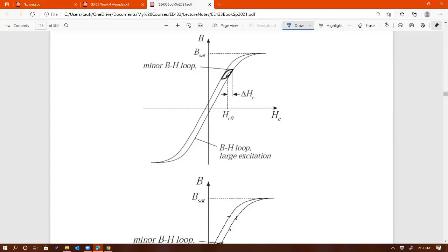So when we operate the magnetic inside the converter, there could be just one quadrant operation, such as this one right here. So we are just exciting the magnetic in the DC to DC converter such that it takes up only one quadrant. It doesn't go to the negative portion of the BH loop.